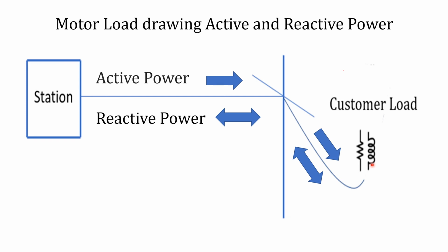Surprisingly, however, the losses from conductor heating in this circuit will be much more than twice as much as the losses in the water heater circuit. Luckily in this case, however, the losses caused by the reactive current flow can be compensated.